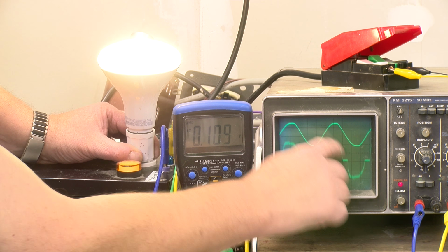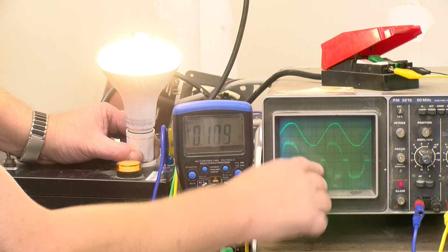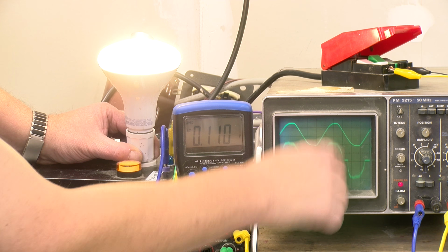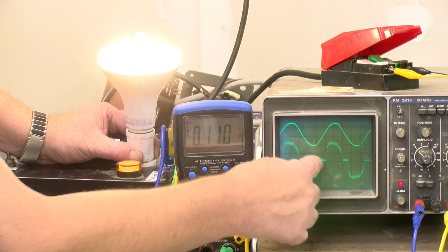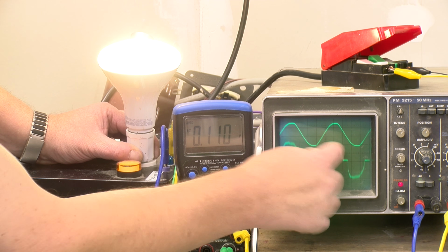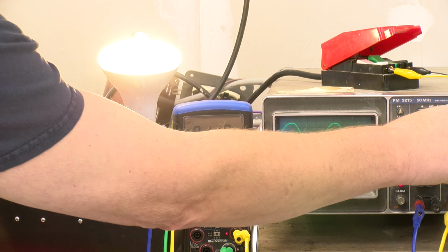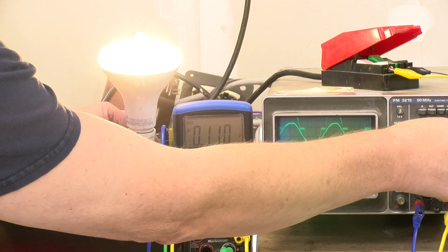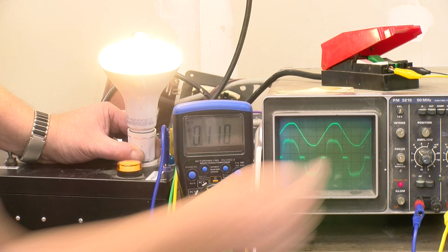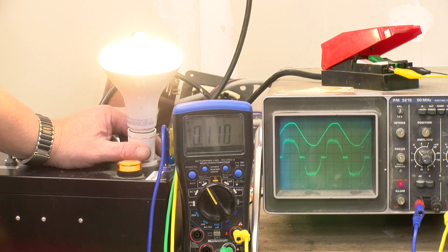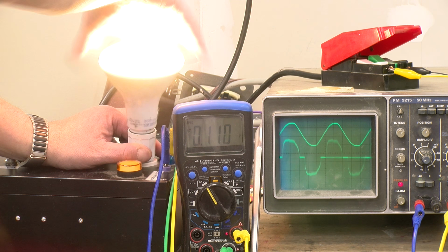And what I can imagine here is they've done some sort of a correction in the power supply to make the current drawn into a much wider pulse. And you can see that it is really getting to resemble a sine wave other than these two things. So, a few harmonics, but the power system would probably be quite happy with that.